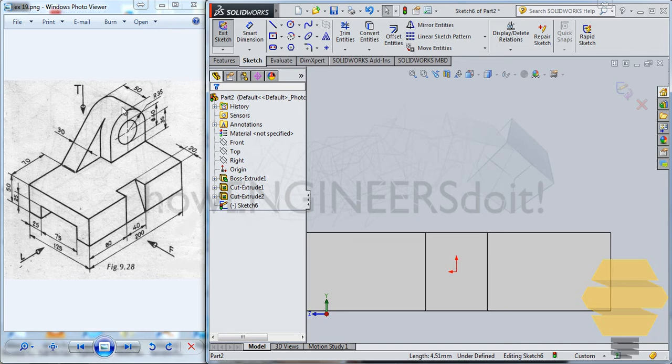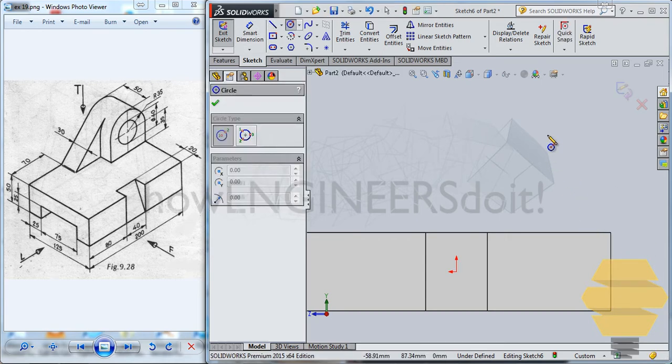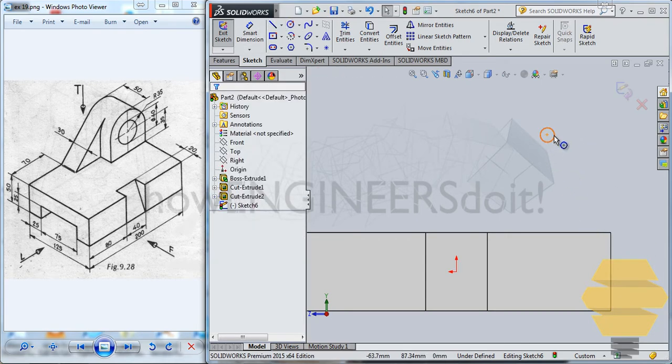You can do it in both ways. Like, you can create this portion here and extrude and make it this much, and then create another sketch and extrude it and make this portion. Also, you can simply make this whole thing and then create this. That's your personal choice. So in my case, I would just go for the first option. So I'll create a circle here,